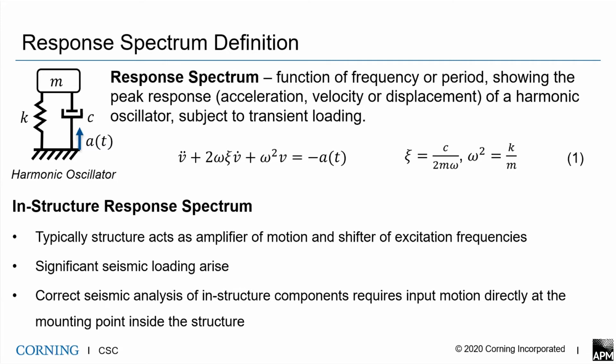But in addition to whole structure seismic analysis, another important task nowadays is seismic analysis of structural components. In many cases, equipment installed inside a building is subjected to significant seismic loadings, which can cause large economic losses. Significant seismic loading arises because typically the structure acts as an amplifier of motion and a shifter of excitation frequencies. That is, in a structure, seismic motion usually has higher amplitude values.